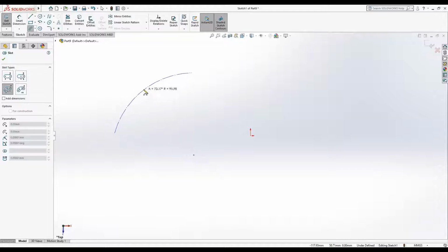That's also going to choose your radius. You can see there's a little plus sign there. That's where the radius of your circle is. If you pull it in there, you can see that we have a 90-degree arc at that point. So when you click the third time, that gives you the arc of your line. And then as you pull out again, it gives you the width of the slot you're going to cut.